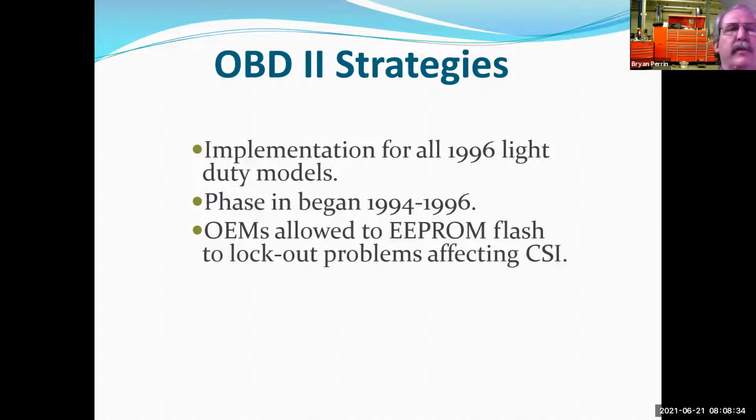So if we're testing our EGR valve, but the customer complaint is the vehicle surges at idle and surges at cruise or going down the highway, and we're getting a lot of complaints on that because that's when we're testing our EGR, we might change our EGR testing strategy or stop testing it altogether. And that can be approved by the federal government based on customer complaints on how the vehicle drives.